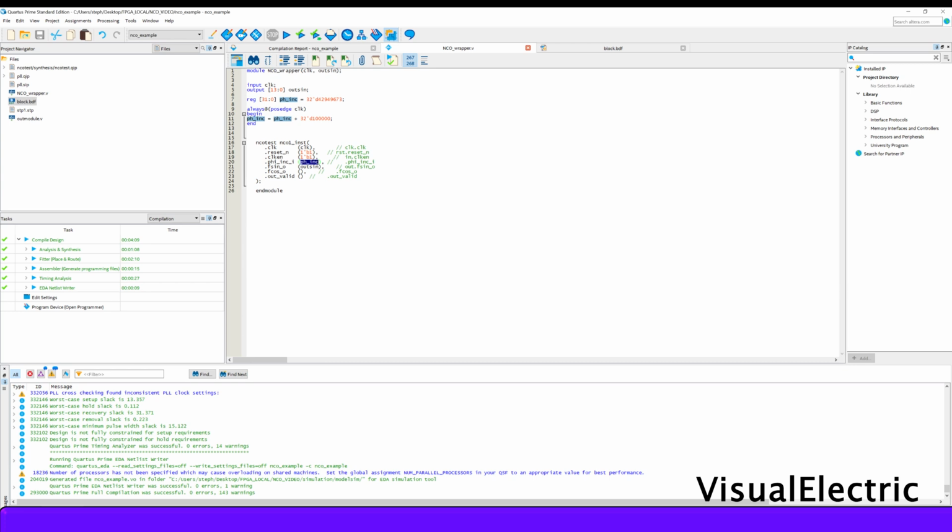This is something which is quite useful in some applications. One that springs to mind is LoRa, the new LoRa communication standard, which uses a chirp waveform. So very simple to do. The NCO gives you the flexibility to actually change the output frequency in real time. And again, another great application of this is just a signal generator. So it would be so simple to have a push button or some kind of input which changes this to whatever frequency you want it to be. So that's another kind of neat trick that you can do with the NCO.